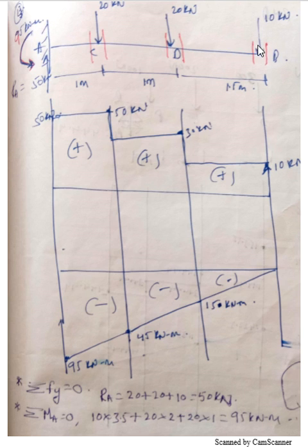on the beam. Here in this example, in cantilever beam, since there is only one support, I am going to get only one reaction at this support. But apart from reaction, we will also get a reaction moment at this support. Rest all calculations and the method of drawing SFD and BMD are going to be same.